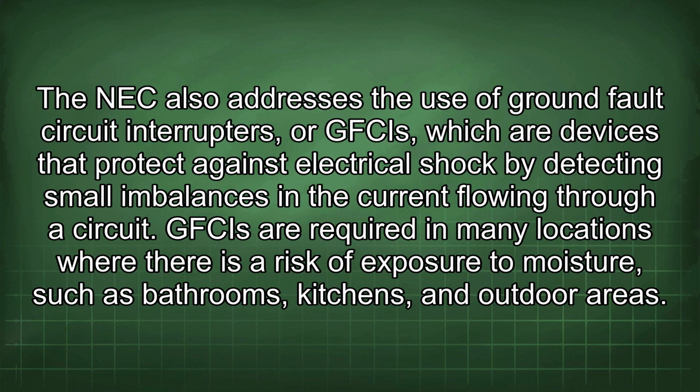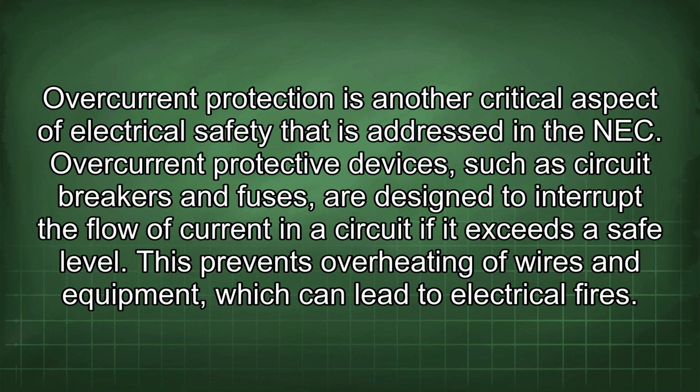The NEC also addresses the use of ground fault circuit interrupters, or GFCIs, which are devices that protect against electrical shock by detecting small imbalances in the current flowing through a circuit. GFCIs are required in many locations where there is a risk of exposure to moisture, such as bathrooms, kitchens, and outdoor areas. Overcurrent protection is another critical aspect of electrical safety that is addressed in the NEC.